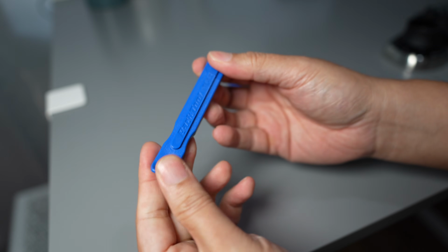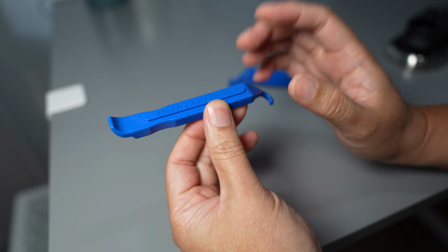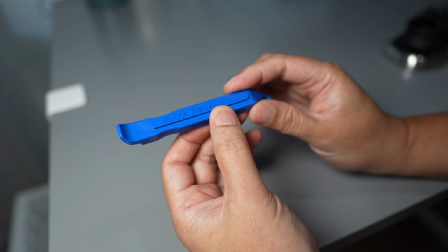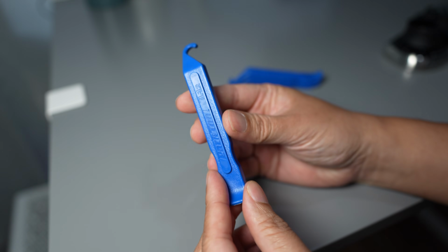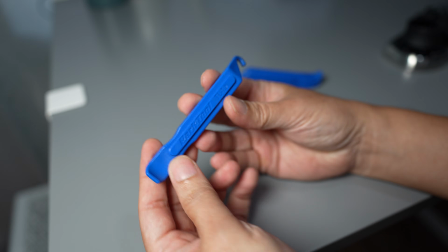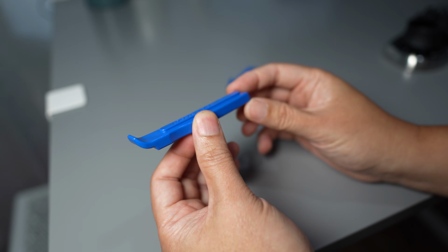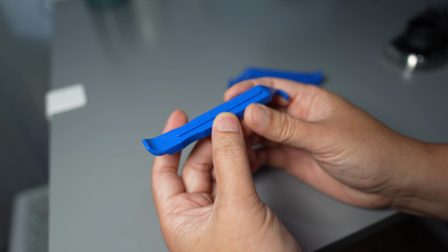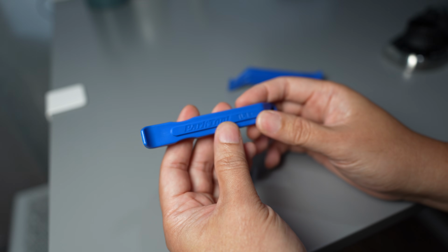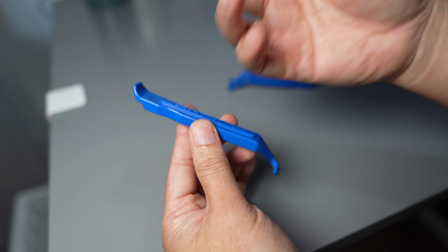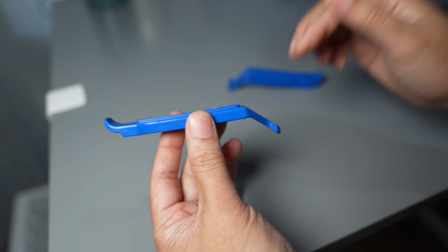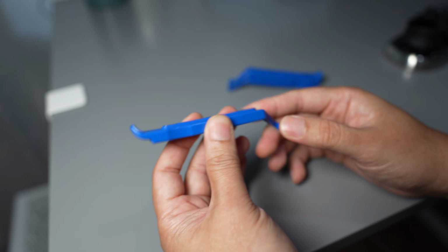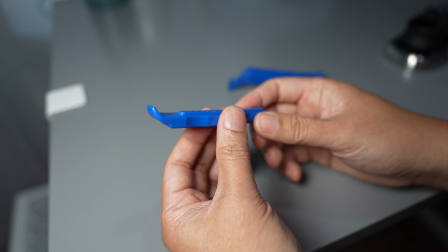So there are two parts. I will start by 3D scanning this part using the Matter and Form 3D scanner, and then I will reverse engineer it in FreeCAD. After I reverse it, I will do the finite element analysis, which is one of the functions in FreeCAD. It could be very useful. You can design for the stiffener and the thickness. When force is applied to this lever, you can predict and simulate the result in advance.